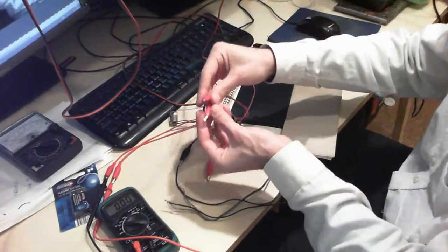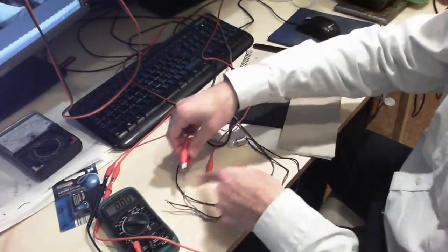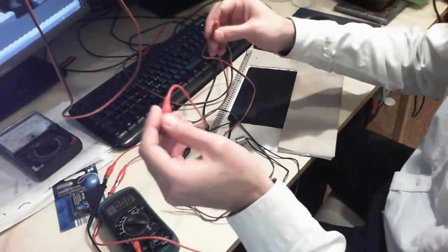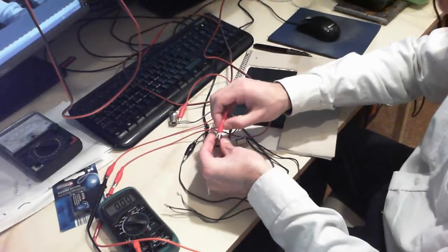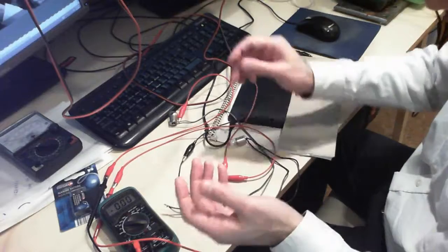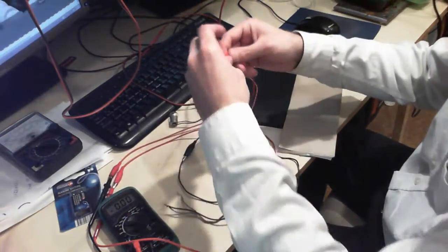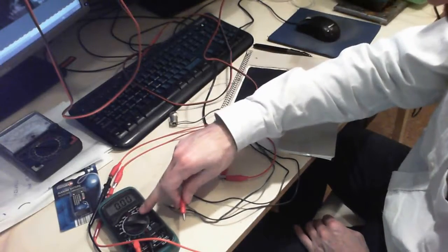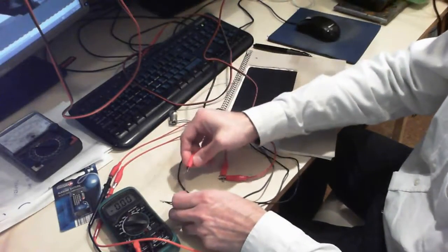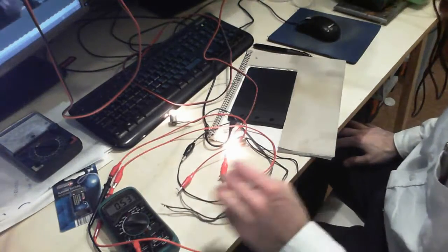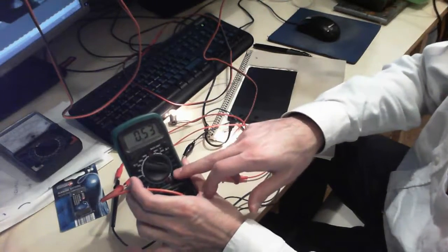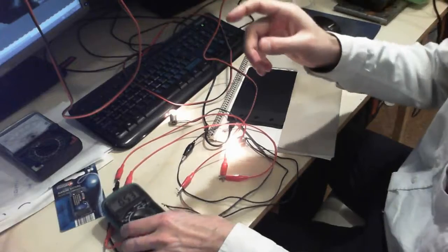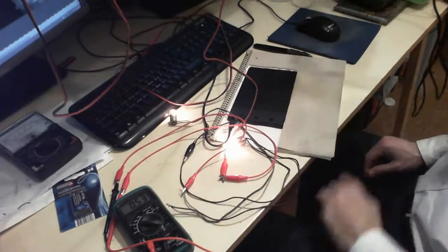And then these two wires coming from the amp meter have to go between these two. Now one of them is positive, this one. So I connect it to the positive pole of my circuit, which is coming from the power supply. And the other one is negative, coming from my amp meter. And there I connect it to my circuit. And here you see you are reading 0.53 amps. And that is basically what we read on the multimeter over here as well.